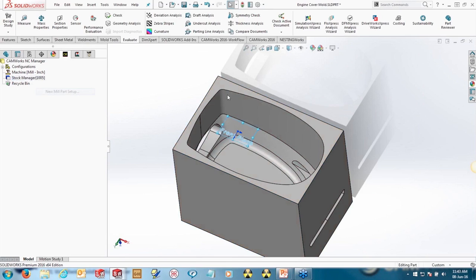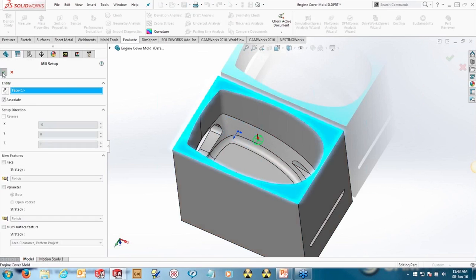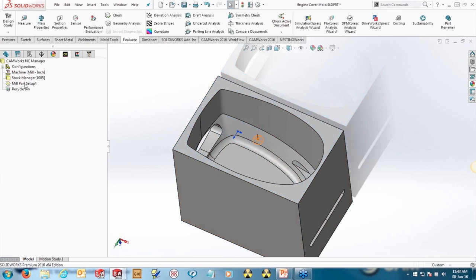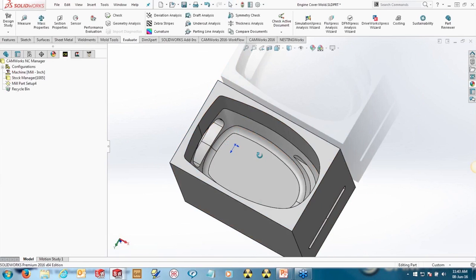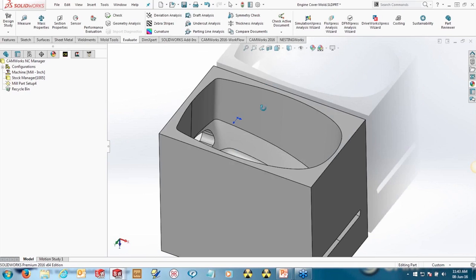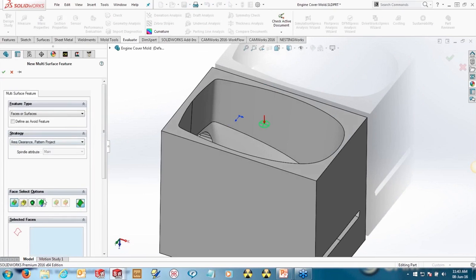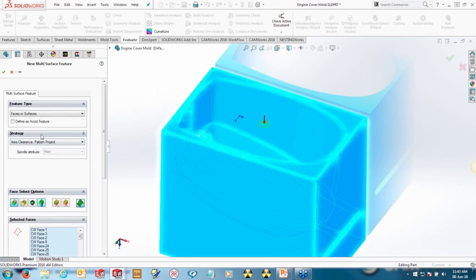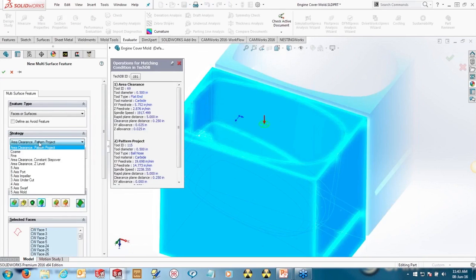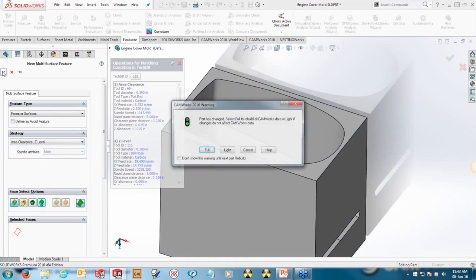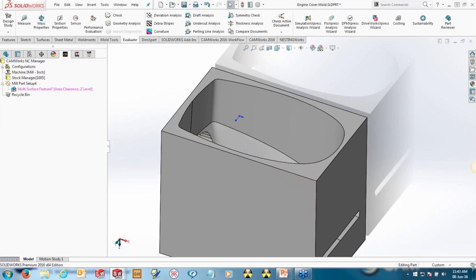So as far as machining it goes, I just want to start looking at programming this. So we'll put in the setup here. There's no 2.5 axis feature, so we couldn't really use feature recognition here, but we can go in and tell it the surfaces to machine. In this case, I'm just going to grab everything. We can still use our strategies in our database for 3, 4, 5 axis as well. Basically, in this case, I'm going to use a 3-axis rough, and a constant step down on the Z. Let's just get rid of this.